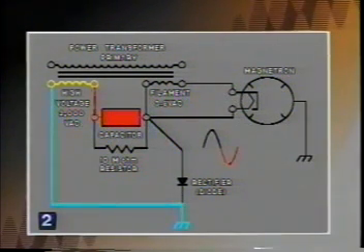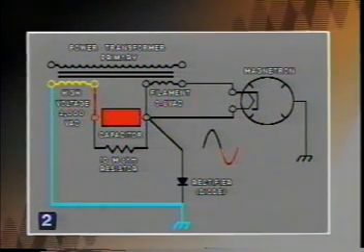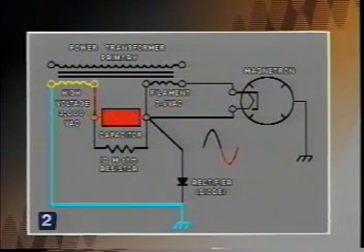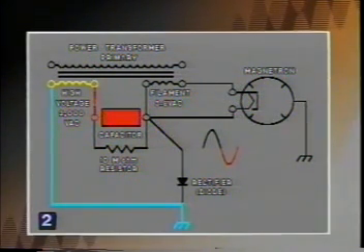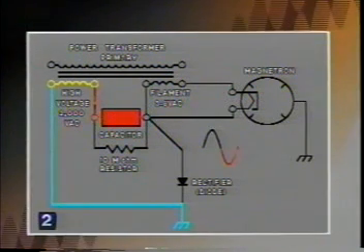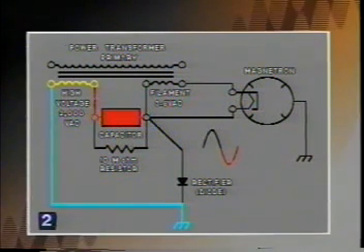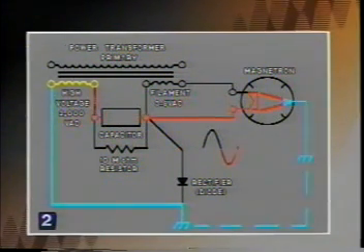During the negative sweep of the alternating current, electrons will flow directly from the secondary winding's hot side, seeking the neutral side of the power source again, as long as a complete circuit is available. The high voltage has only one path to follow to get to the neutral side of the power source. With the applied energy from the transformer of 2,000 volts, plus the stored energy of 2,000 volts from the fully charged capacitor, there is enough power to override the high resistance of the magnetron.